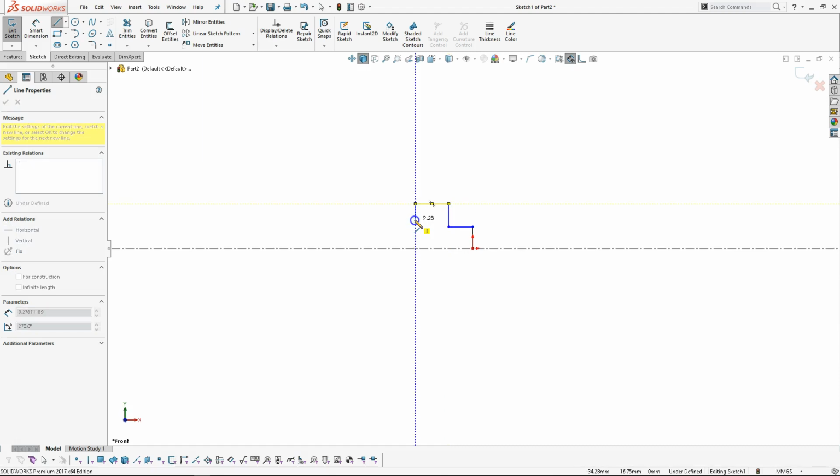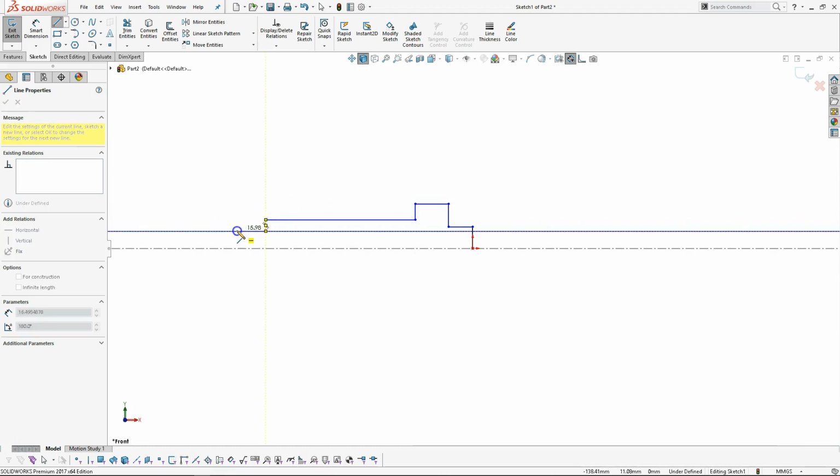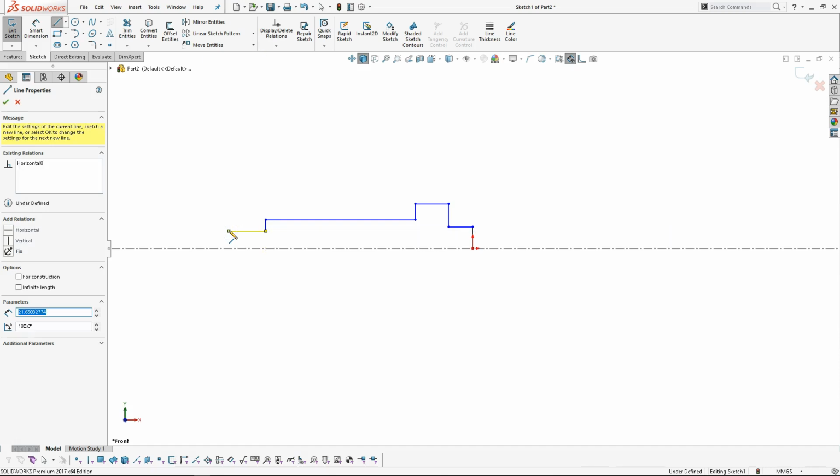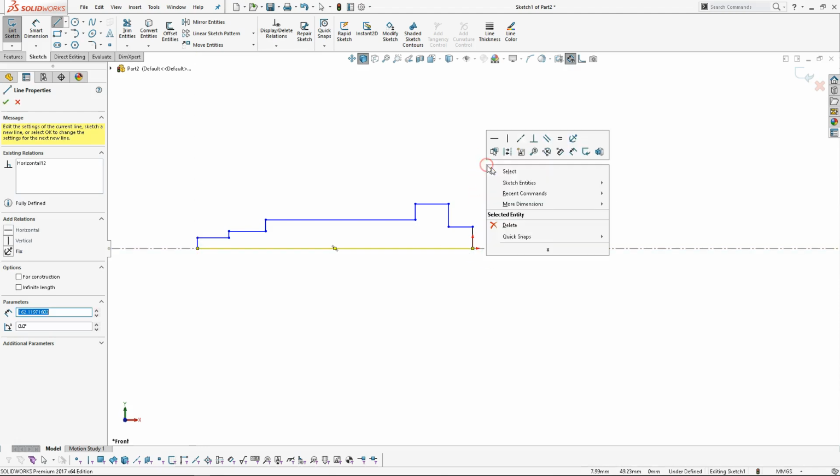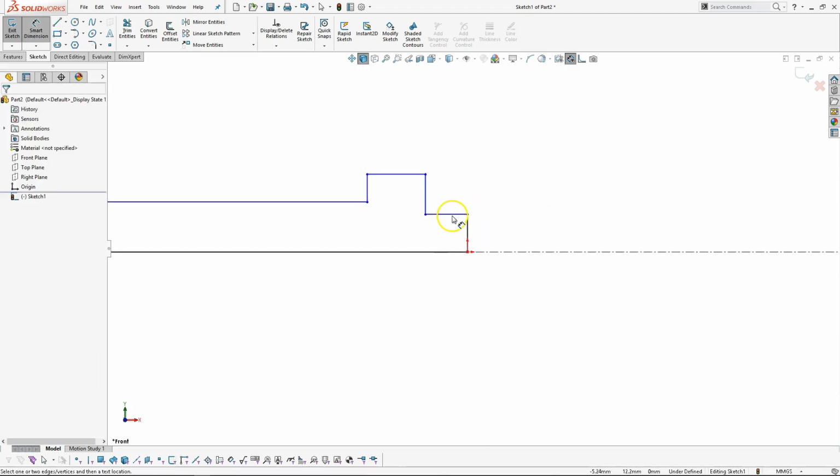And then we're coming back to 17 millimeters for the through, and this is where I need the class of fit. And then there's going to be a jam nut, and from the jam nut I need something that's going to drive into the coupler, and then we're going to close the whole thing off. All right, so I've started putting in some dimensions.